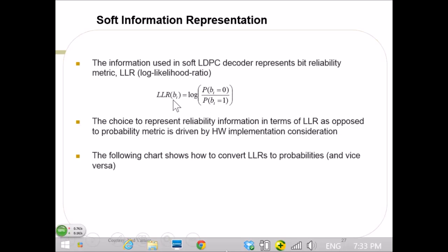So what happens is we compute a ratio called the log likelihood ratio. This ratio is nothing but a ratio of two probabilities. For a binary decoder, there is only one LLR. But if you take a non-binary decoder, like one over GF4, usually the LLR is a vector. So you have three entries in the LLR vector, because for a GF4 you have 4 symbols. If you take one symbol as a reference, there are 3 more symbols that you need to compare.